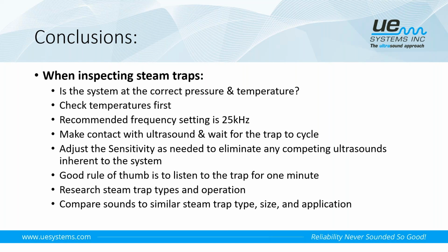So if it's a very low load on the system, or if it's a trap that's only used when things kick on or come on, then it may be hours before that steam trap ever does anything. But a good rule of thumb is about a minute. So you do have to exercise a little bit of patience. Do some research on different steam trap types and operation.